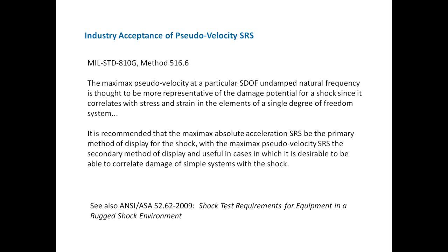So MIL-STD-810G says the maxi-max pseudo velocity at a particular single degree of freedom, undamped natural frequency, is thought to be more representative of the damage potential for shock, since it correlates with stress and strain in the elements of a single degree of freedom system. It is recommended that the maxi-max absolute acceleration SRS be the primary method of display for the shock, with the maxi-max pseudo-velocity SRS the secondary method of display, and useful in cases in which it is desirable to be able to correlate damage of simple systems with shock.